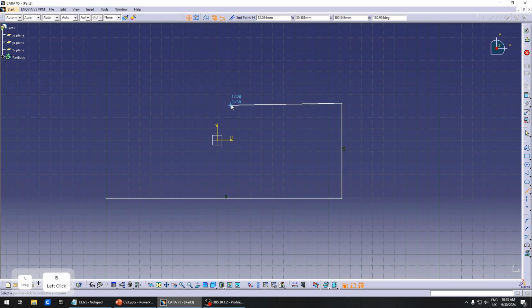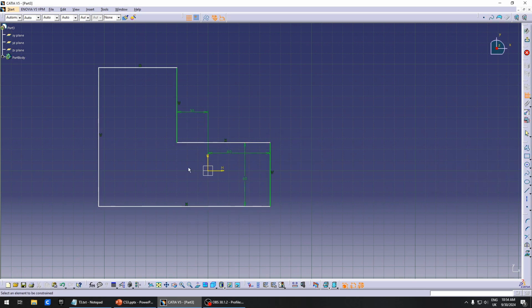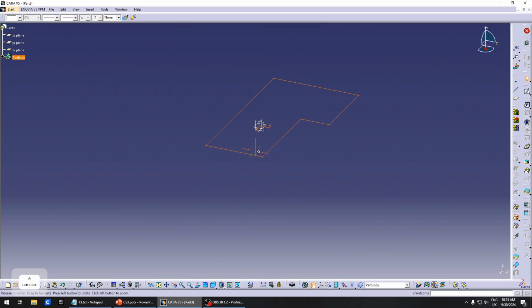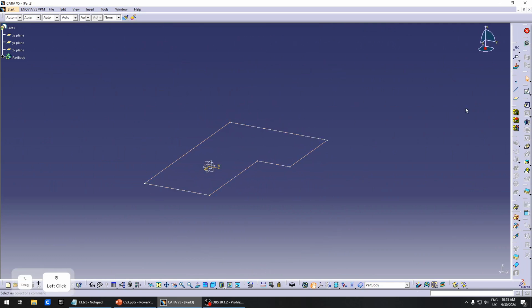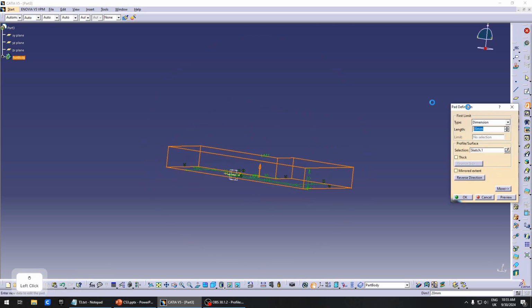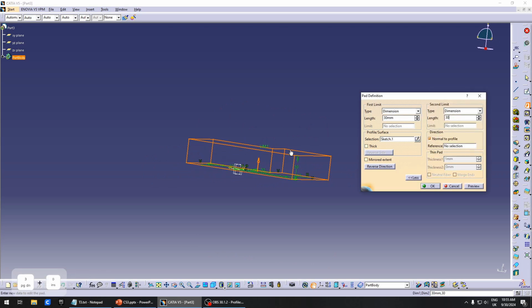We will start by modeling the top surface. I'm going to fast forward a little bit while I draw the sketch because I assume you already know how to constrain sketches. We will be using the automatic snap features a lot. Alright, now that we have our base, we can extrude this. Let's just say for now we'll go 30 millimeters up and 30 millimeters down.